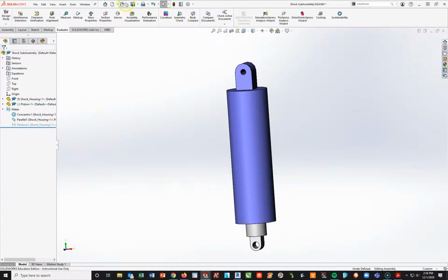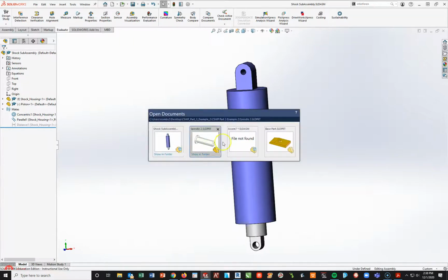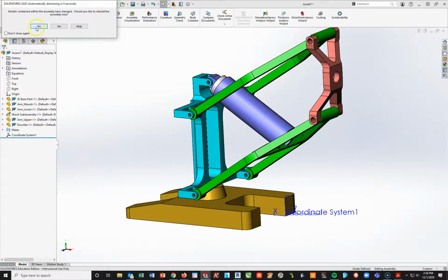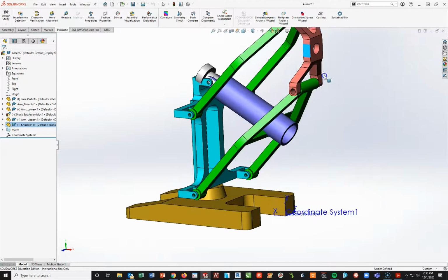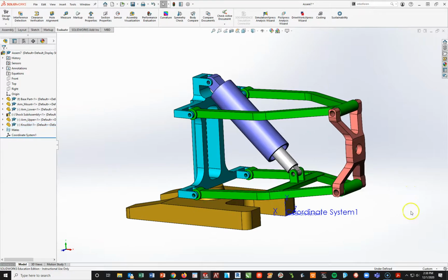Okay, do a quick save here. Rebuild, Control Tab, go back into my assembly and say yes. So now this is free to move around. By taking that distance mate off, I can make this move. All right, now what it wants us to do is suppress that distance mate, flexible in the top level assembly. We've done that. Create the part shown below, and then we're going to add in a couple things.